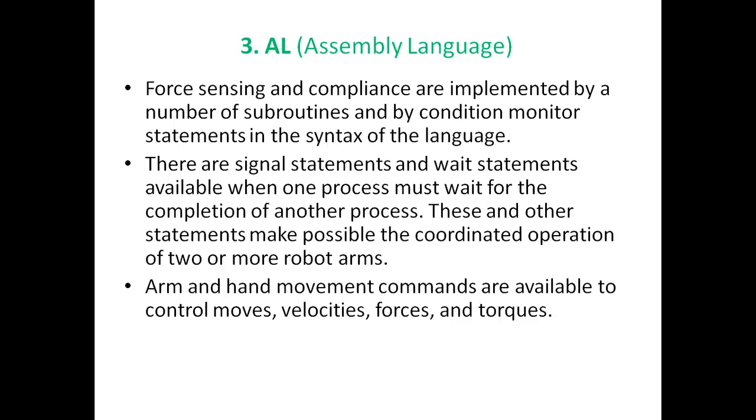Similarly, force sensing and compliance will be implemented in a number of subroutines, and we'll have a number of signal statements and wait statements, if we are having a wait process for the completion of another process.